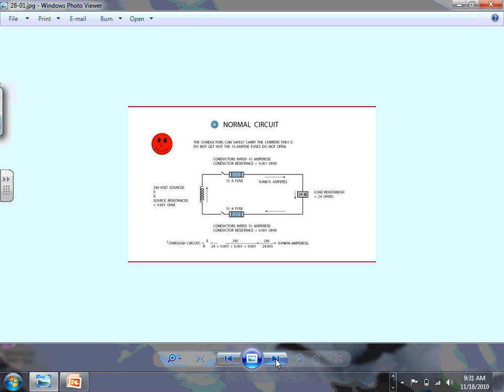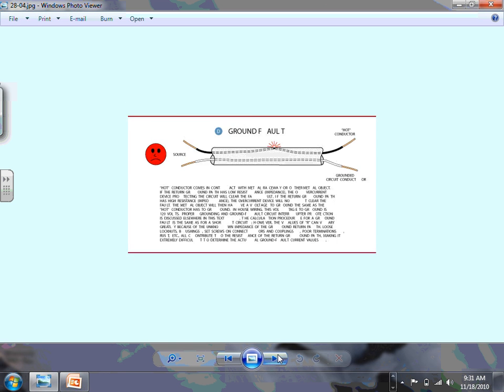The only thing, if it's series rated, guys, the manufacturer has to label it as series rated, not me. If you read the code, engineers can do series rated in the field, but you have to have a study and document it and all the stuff to say I'm going to use a different type of circuit breaker here, and I'm willing to stick my head out and get sued if something happens. Any question, guys?